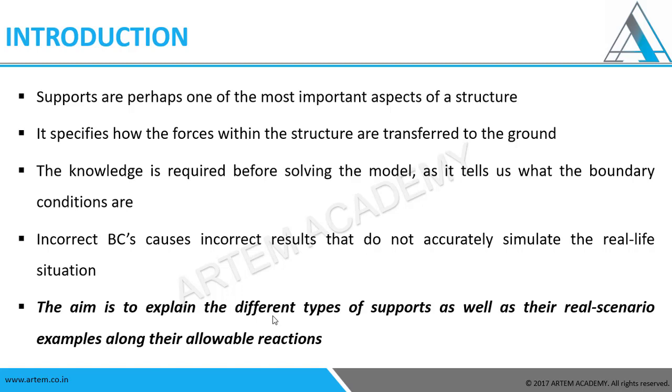According to the functionality of the model and the selection of the component, we have to consider which support is more relevant. Supports are called constraints, which in turn are nothing but boundary conditions. An incorrect boundary condition causes incorrect results that do not accurately simulate the real-life situation. We will be discussing this with examples for each kind of support so that you will get more clarity about it.